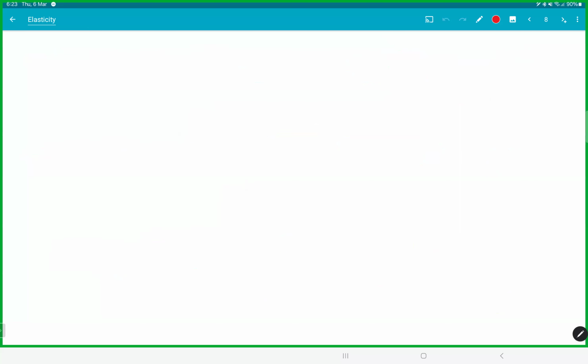Right. So if I substitute here, Young's modulus Y is stress by strain. What is stress? Tension by area, and strain is delta L by L. There, this is your formula. Young's modulus will be T L by A delta L. Now for convenience, I will write delta L as e, because later on when we have to integrate, d of delta L looks pretty weird.